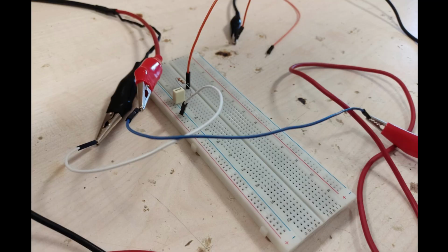In conclusion, with this experiment, I was able to observe the effects of frequency change on the capacitive reactance of the capacitor and the current in the circuit by simply constructing a circuit including the resistor and the capacitor by using an alternating current circuit. In this experiment, my errors were in the range from 0.39 to 16.90 for the current and from 0.37 to 22.09 for the capacitive reactance of the capacitor.